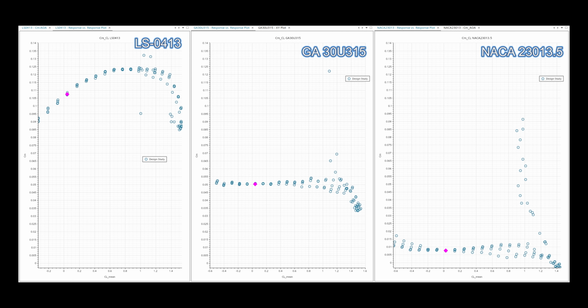2. Stability evaluation. Pitching moment, CM. When CL equals 0, CM0 is positive. This means that under zero lift, the pitching moment about the quarter chord, 1/4 C, is positive, i.e., the main wing produces a nose-up moment. To maintain equilibrium, the tail must provide a nose-down moment.